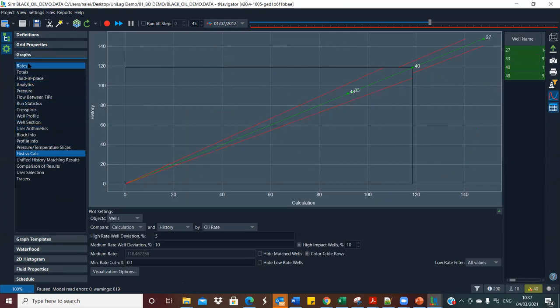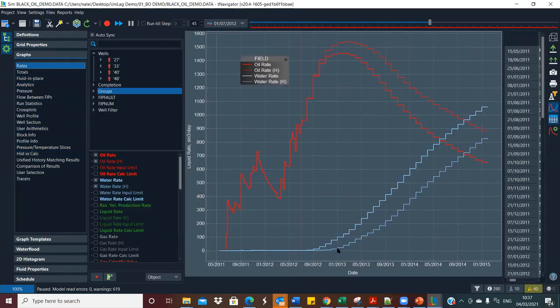And quickly, you may want to start thinking of playing with your relative permeabilities. In this case, you see you have water that is arriving earlier than the historic, the measured one in the field. The model is giving us earlier water arrival, so we may want to delay, slow down the water, in the field, okay?